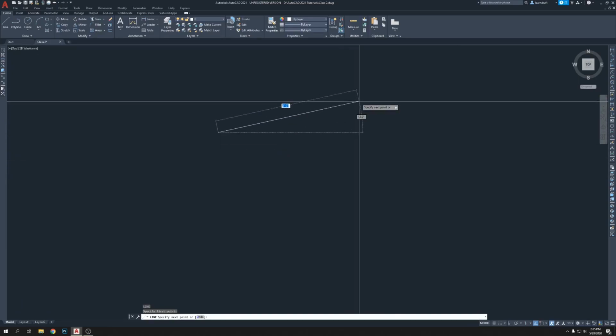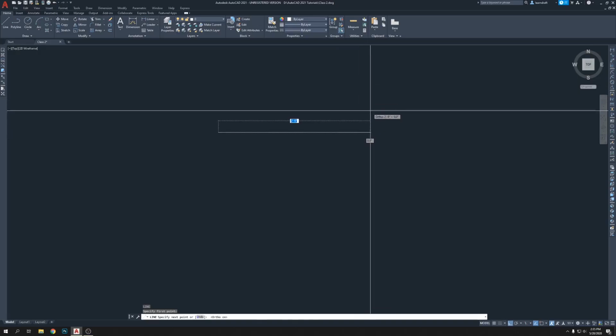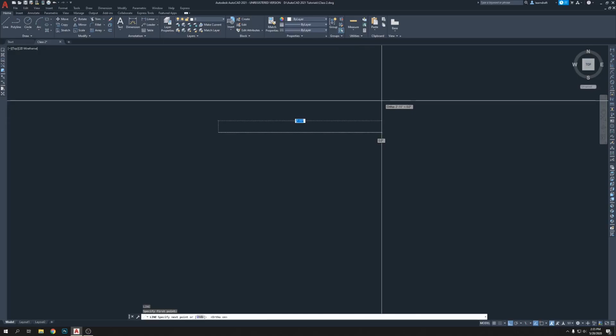Now if you look at the paper I asked you to print, today is V2, main video 2. Open the file and draw a line, then use F8. F8 means the F8 button on the keyboard. If you press it, the line is going to be straight. But you don't always need a straight line; sometimes you need a cross line.